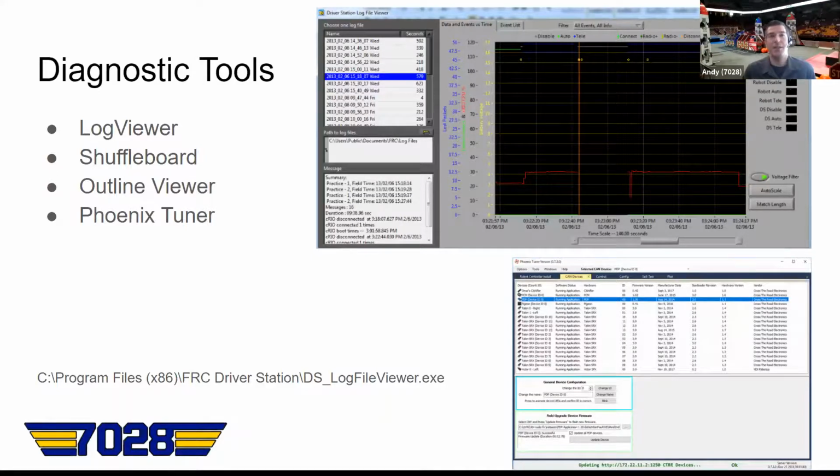So you can have essentially no code on your robot, just this Phoenix Tuner installed on your robot. And you can go to the self-test tab and select a motor controller and say, I want to run it at this speed, and it'll run it. So we did that here and there to figure out, did we have a wiring problem?